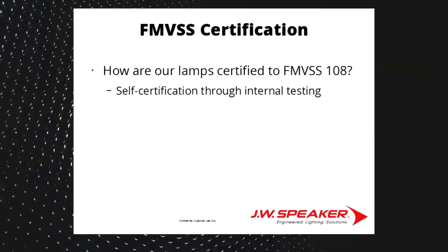So how are our lamps certified to this? It is self-certification through internal testing. So we take our lamp, we photometrically test it here, it passes the test, we put DOT on it, and we say we are certified. The government does not do any certification.